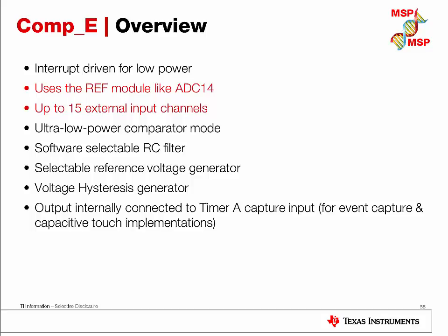The output of the comparator E is also internally connected to the Timer A capture input. This way you can create an event capture or use it for capacitive touch implementations. There are two instances of comparator E provided in the MSP432 P4XX family.